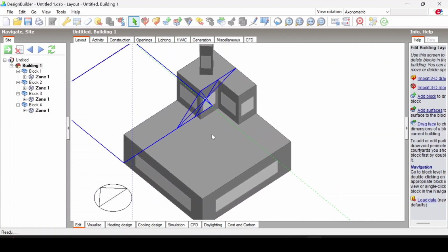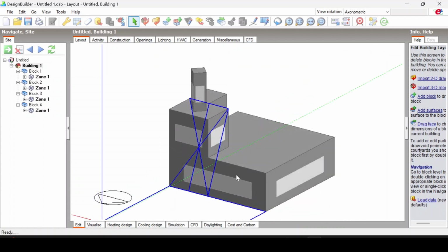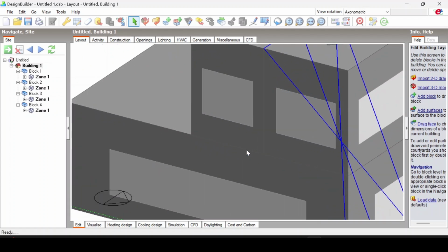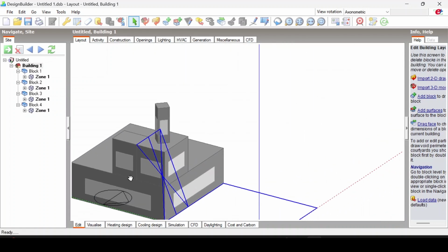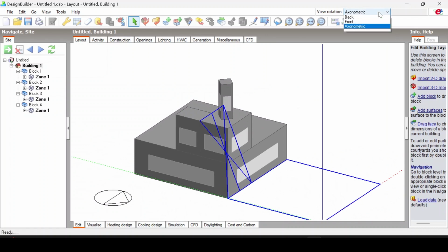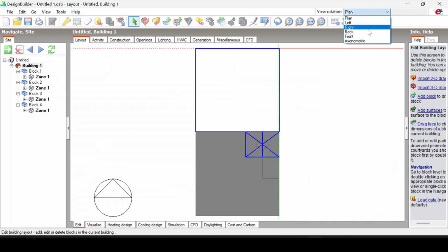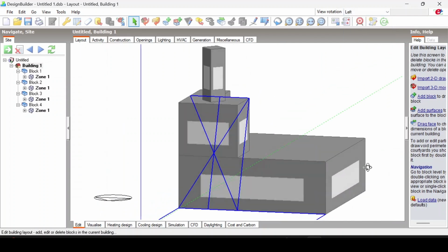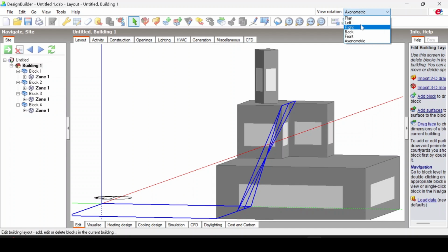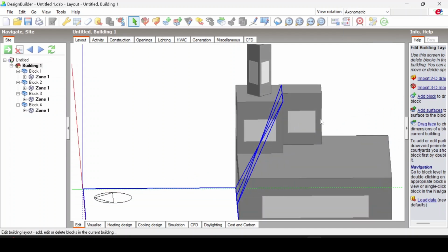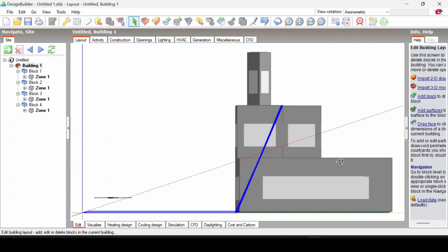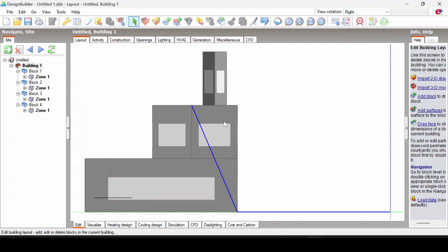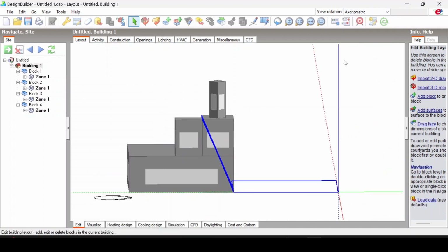So in that regard, you will not find any situation where you are not able to see the particular section of your object. Either for seeing the particular section or drawing on the particular face, you can rotate it. If you want to draw, you can rotate it, or zoom in or zoom out, or else you can move it. Or if nothing else works, you can select the face plane. If you want the left side of this one, you can see which side it is taking as left by rotating it slightly. So you can see this side is left, then right will be the opposite of that. In this way you can select the particular object and draw.